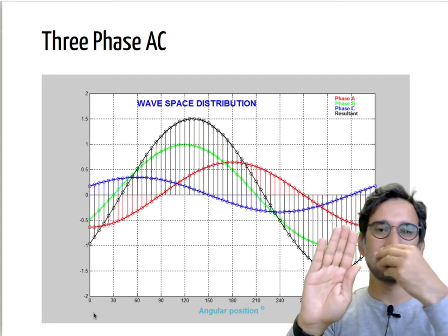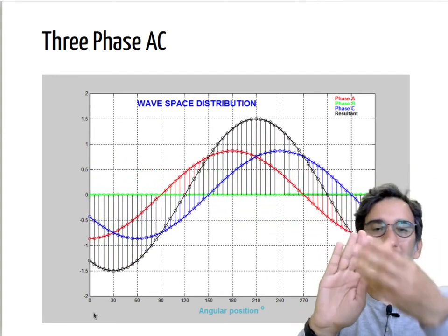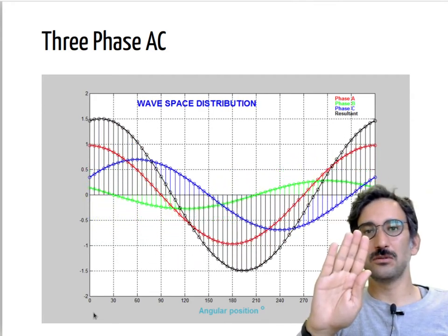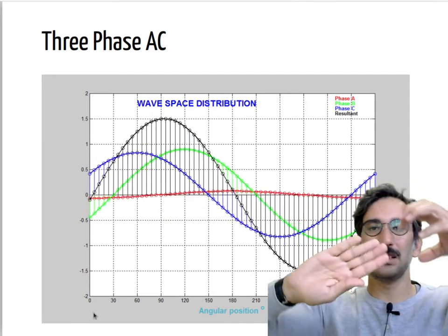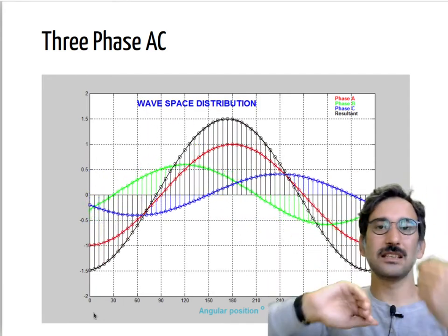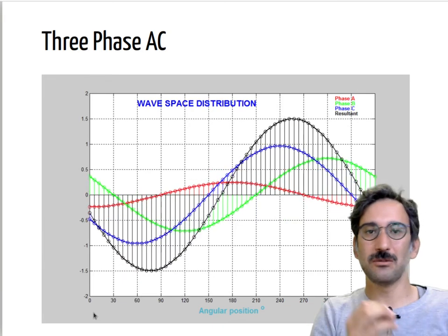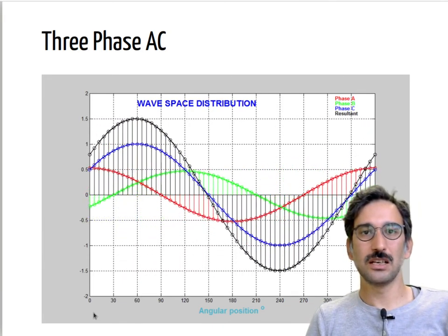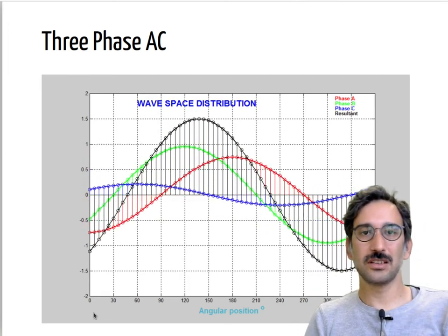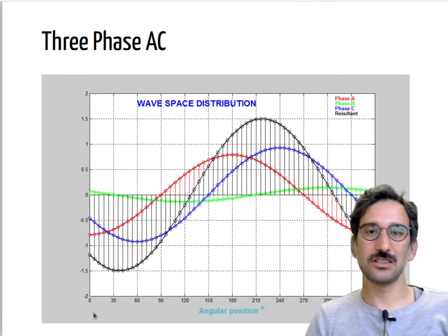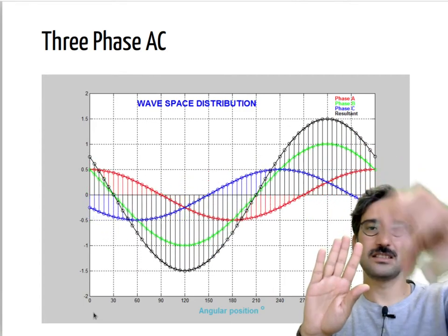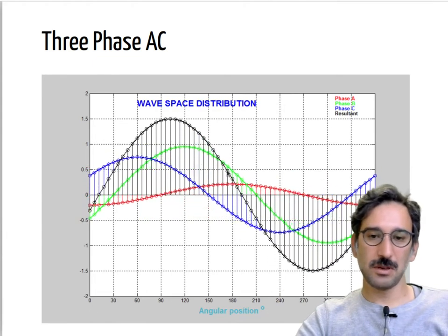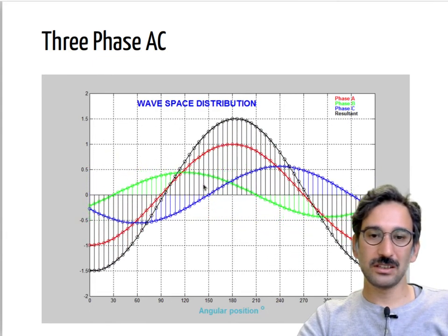But actually that waveform shows us that without any moving parts, just using coils and a clever way of exciting those coils, the MMF will have the same effect as a rotating magnet. That is where the term comes from, rotating magneto-motive force, or in other words, the equivalent magnetic field of all these three stationary coils creates the same effect as taking a magnet in your hand and trying to rotate it with some speed. Maybe it will be clear with the phasor diagram.